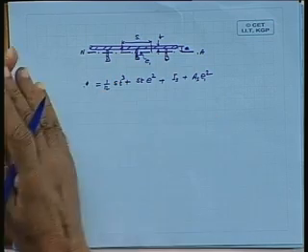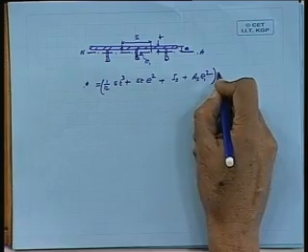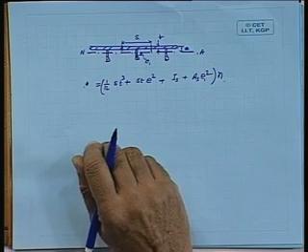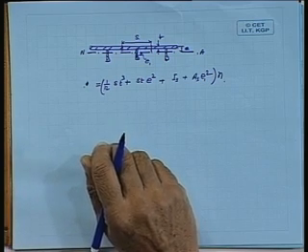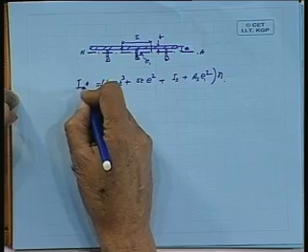Okay. Now if the width of the bulkhead beam is divided into n number of these spaces, then this total multiplied by n gives me the total I of the plate about xx.